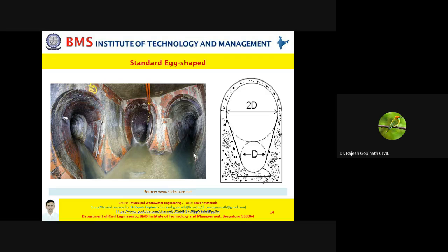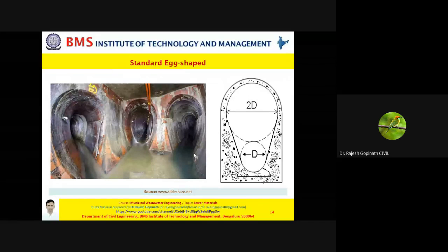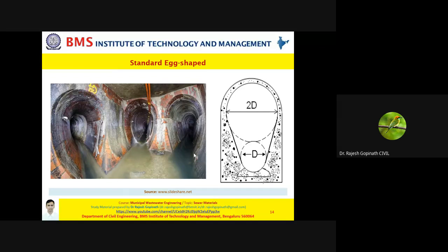In fact, even your circular sewers cannot attain that. So the advantage is, when compared to circular sewers, if I have an egg-shaped sewer of the same capacity, these sewers are the ones which can generate higher velocity even if the flow is very little. That means, again, we are stressing dry weather flow. So please understand, in my repetitions, I'm trying to stress that one selection criterion has been met, that is creation of self-cleansing velocity.